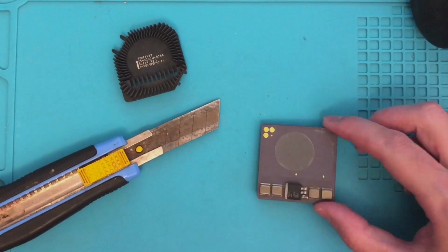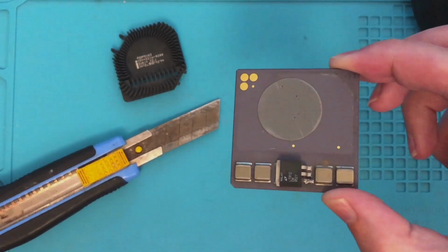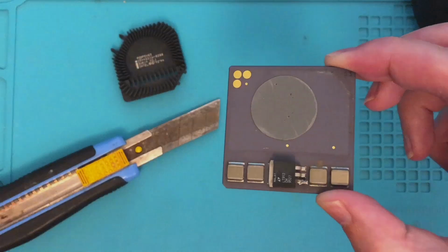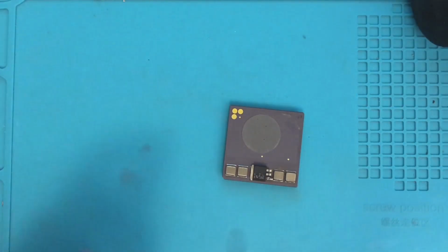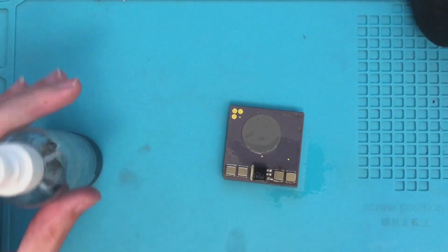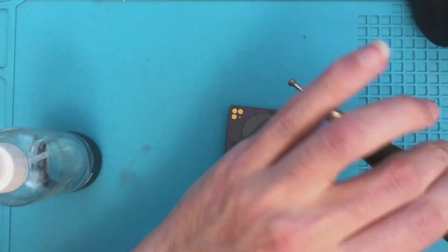However, this is where the real pain begins. You see, this glue here is something like ceramic cement, so it's really like a stone, and it doesn't glue that strongly to the metal, but to the ceramic CPU it is a totally different story. So now, if we want to use any serious cooling here, we have to make this surface flat and remove this gray stone thing here. I tried to scratch it with a knife or something, but it doesn't really help. So in the end, the fastest way, and a little bit brutal, is by using a Dremel with a diamond tip.